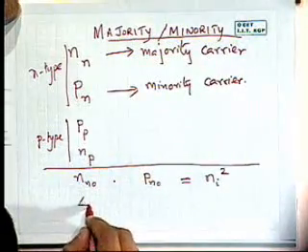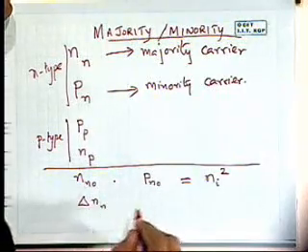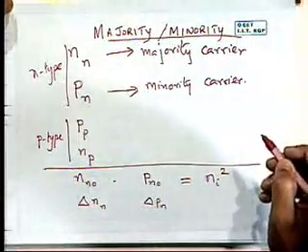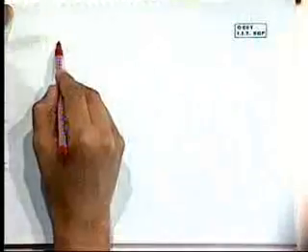And then we also had the notation of the instantaneous change in the carrier concentrations. For example, when we illuminate the semiconductor with a light that is sufficiently strong as to cause excitation across the band gap, all of a sudden we've got extra electrons and holes that are created in equal numbers, EHPs, as we refer to them. What I ended up pointing out the last time was that there is a very drastic change in the carrier concentration that takes place as a consequence of this illumination or injection of carriers. I will just briefly go back to it.